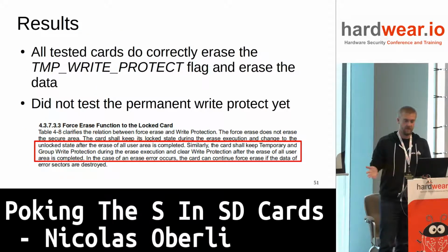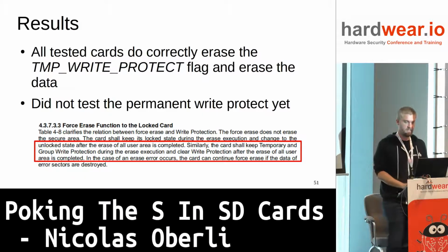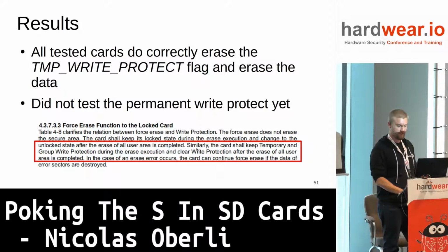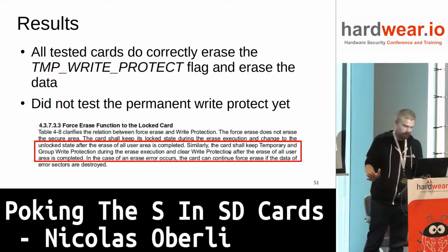Fortunately, all the cards I tested did a good job. They basically followed what is written in the specs. Similarly, the card shall keep temporary and group write protection during the erase execution and clear write protection after the erase of all data is completed. So they're doing a great job.